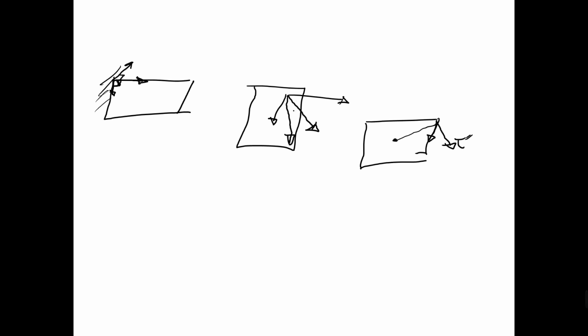That resultant is in the plane, and anywhere in the plane, this tertiary shear will always be perpendicular to this resultant. So if we have a case of three, we need to calculate the resultant of primary and secondary, and then from that resultant, the square root of tau square plus tau triple prime square gives us the maximum tau in the weld. So this is the method of calculating.